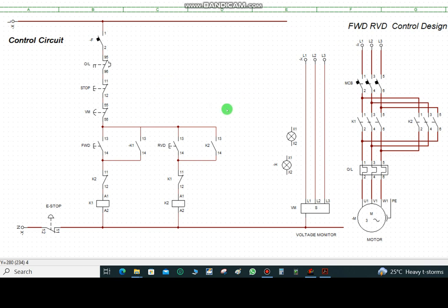All right, now let me just recap about this again. The relationship between here and here is what I'm going to disconnect now. Let me take it away. Now, this is direct online setup, right? And this is the branch circuit we just created for the reverse operation to close this contactor. Just for us to close this contactor, that is why we have this branch here. So what we have here is what we replicate here.